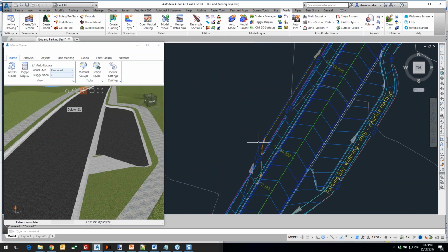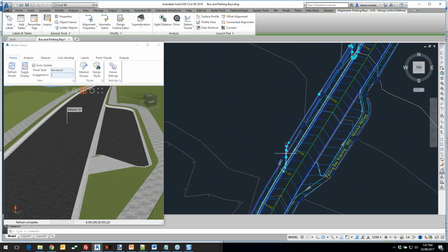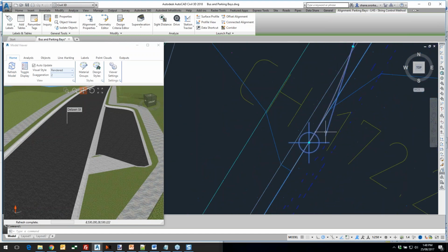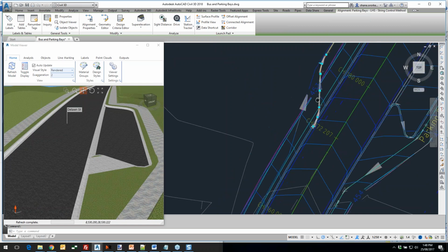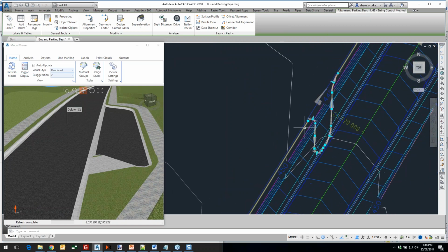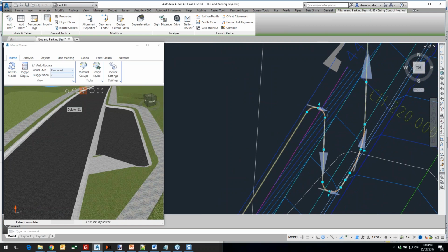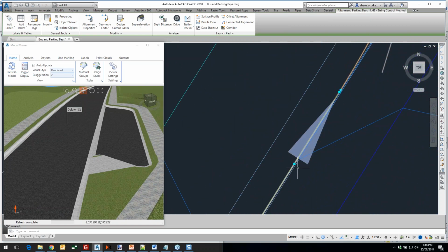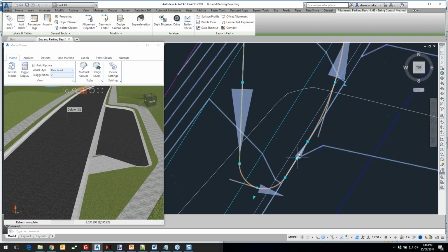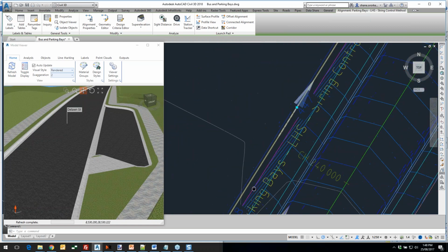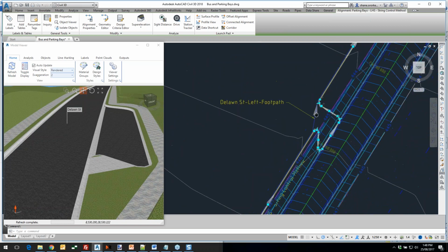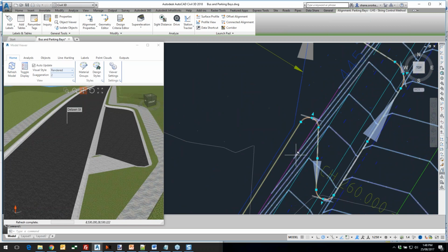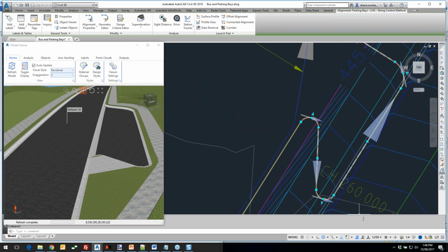Okay, so I have an alignment here. This alignment actually cuts in at the invert of the road, because I'm happy to keep the invert going through. I want a dish, and then it rolls out, and then it rolls back in whatever shape you want, up to just a small smidge off the invert. So pretty much going back to the invert and then coming away, and then going back to the invert again. Now, just to keep it interesting, I've got some 90-degree angles here. I've got some 60-degree angle bays. So the shape could be whatever you want it to be.